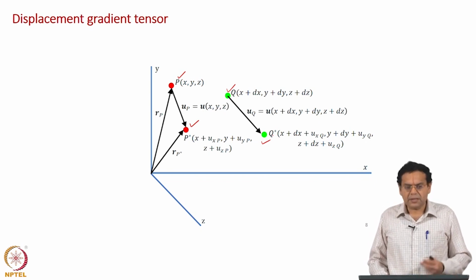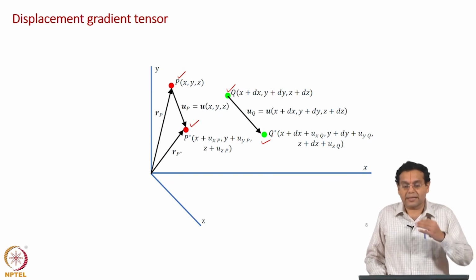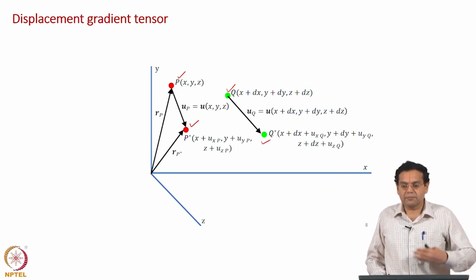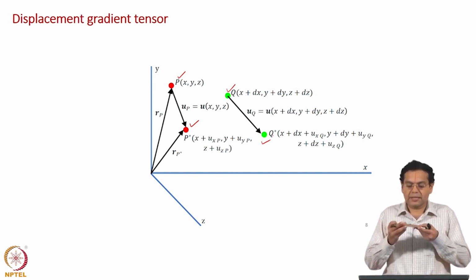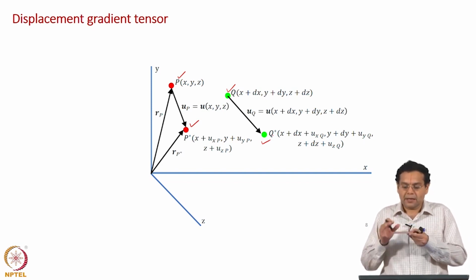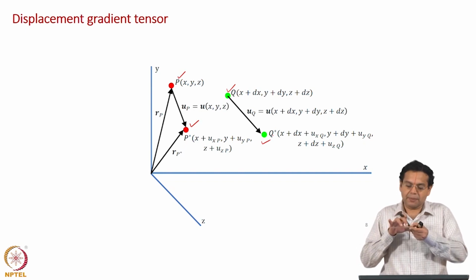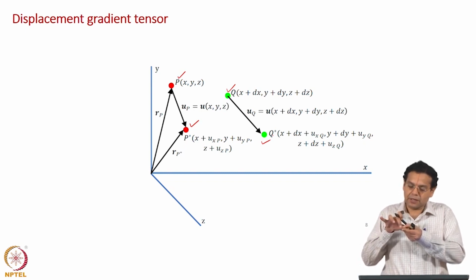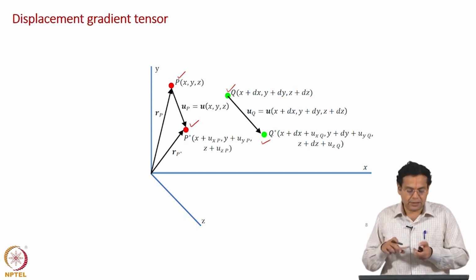Now, our objective is to split rigid body motion or take away rigid body motion from the deformation. First thing what we will take out is translation. What is translation? If you take, let us say, a plate and it moves along one direction, every point, let us say if you focus on 2 points, both the points move by the same distance. Let us say the plate moves by 5 centimeter, and you focus on these 2 points, both the points move by 5 centimeter. Okay. And that is what is shown here.